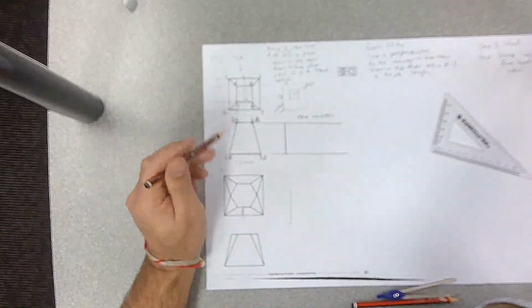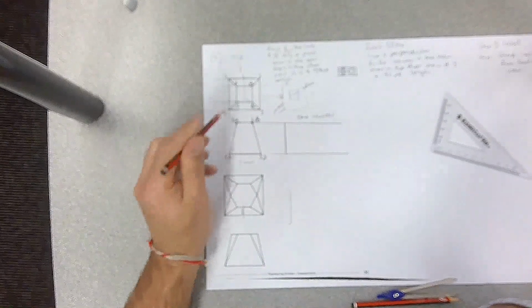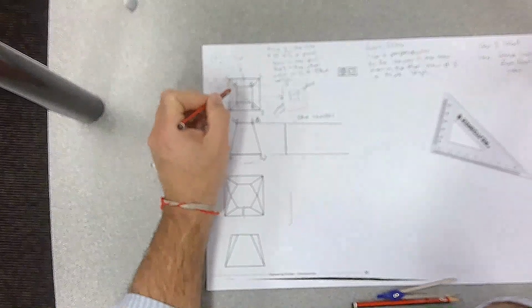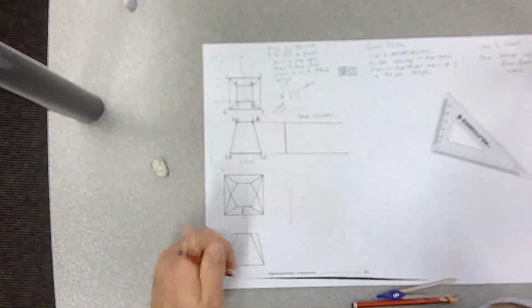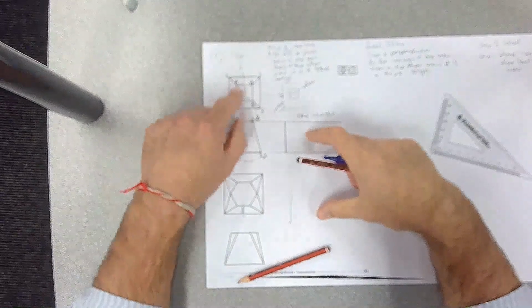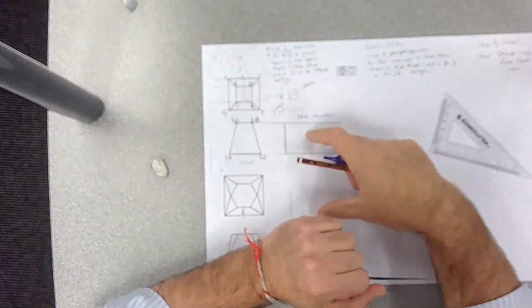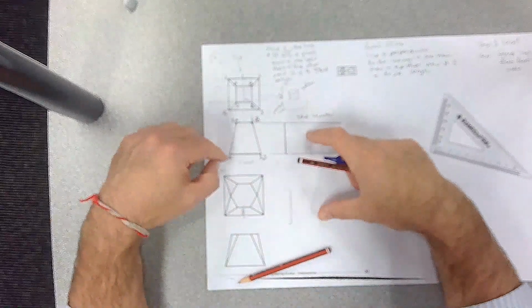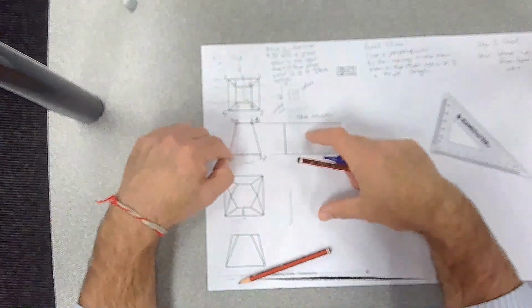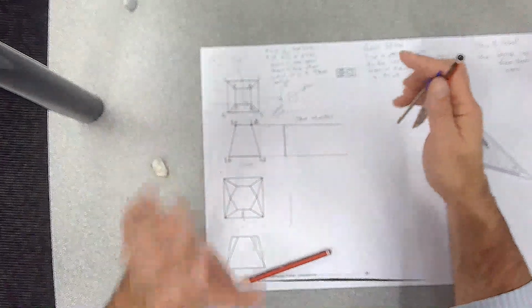Now you need to decide on a line that you're going to start your whole process for drawing your development, and I'm going to decide to use this line 1A. Now the only trouble with that line is that it's neither a point view or perpendicular to the viewer in any of the views. So if you look at 1A on this diagram here, it's not perpendicular to the viewer and it's not a point view, so it's not a true length. How do you find the true length?